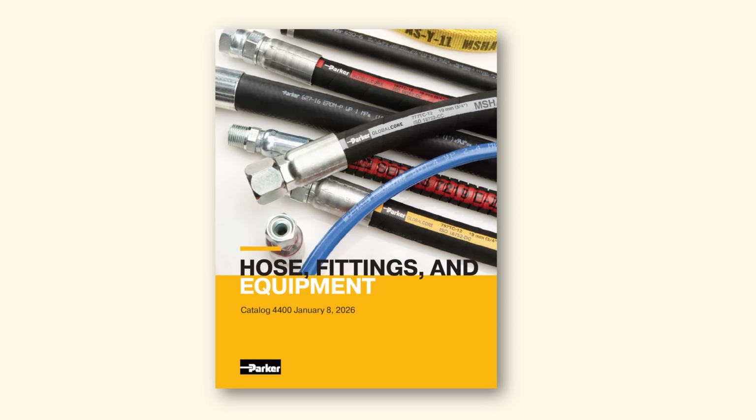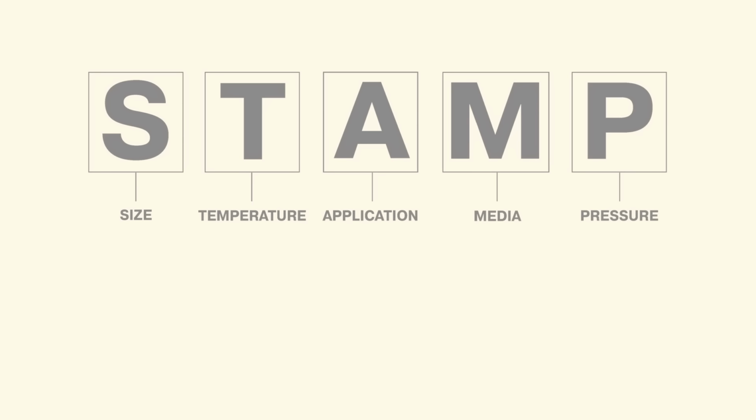And now let's understand how to select the hose part number from the manufacturer catalog. In this video, we will select hoses from Parker, a well-known hydraulic hose and fitting manufacturer. Now, to select the hose from manufacturer catalog, hose size alone is not enough. We must consider the full stamp. First, the size. From our calculations, the required hose size is 3 by 4 inch.